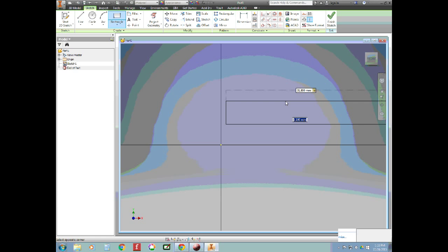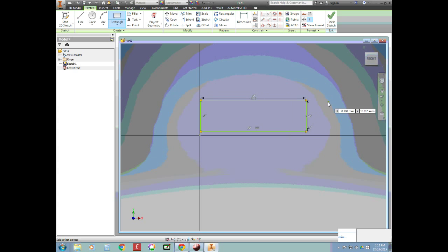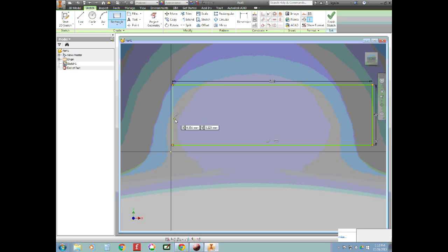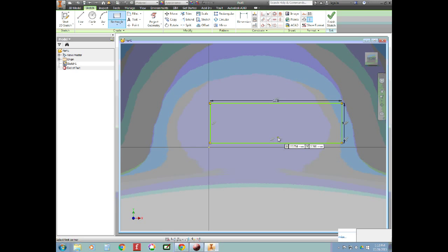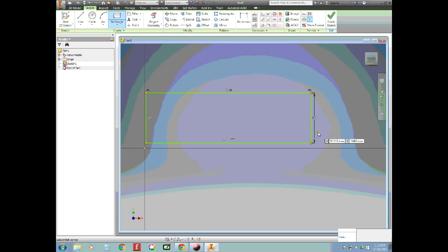And this was 9.6, I believe. And then press the enter key. Now, we've got some things here to talk about. This version, by default, leaves what's called the geometric constraints on, showing you what geometric constraints are automatically applied. So this one and this one are parallel to each other. That is this constraint right here. And this line are parallel to each other. This line is horizontal. And it's showing the perpendicular constraint as well.